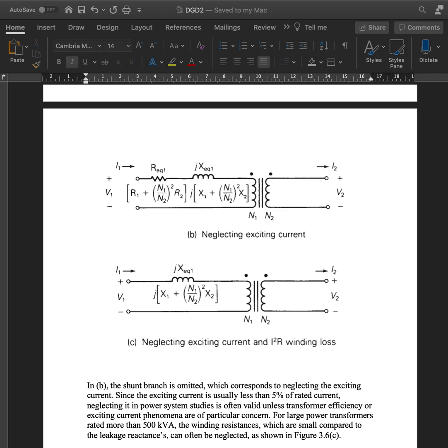And thus a practical transformer operating in a sinusoidal steady state is equivalent to an ideal transformer with external impedance, which would be anything connected to the secondary side of the winding, and admittance branches, as we can see in this figure right here. We can even evaluate the external branches, like the one we have right here, in terms of short circuit and open circuit tests, which we'll look through in an example just below.